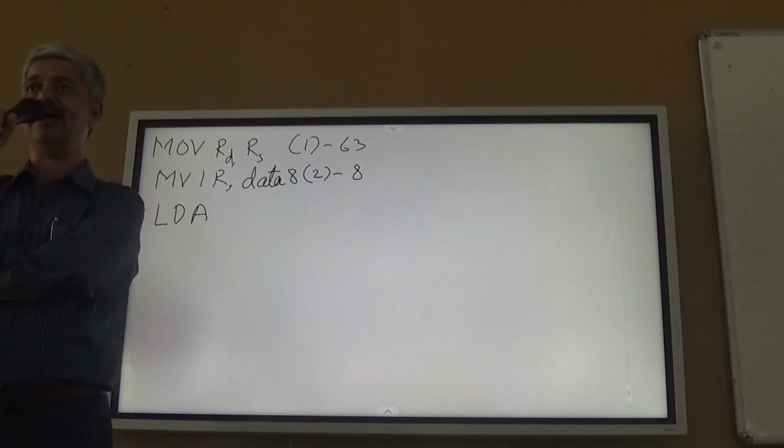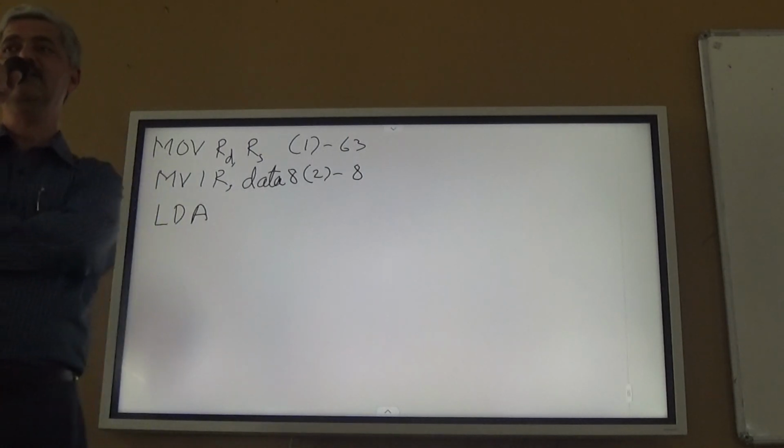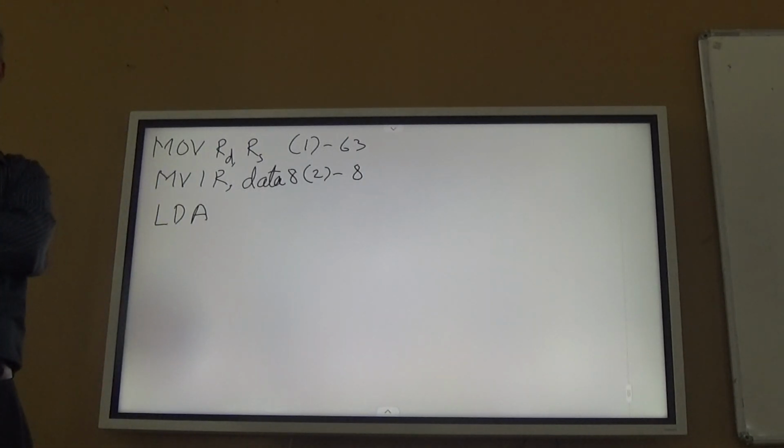So the first byte obviously the opcode, and what should be remaining one? How many byte instruction should it be? 3 byte. Why? Because a 16-bit address should be provided as a part of the instruction. So what should be the format of the instruction?